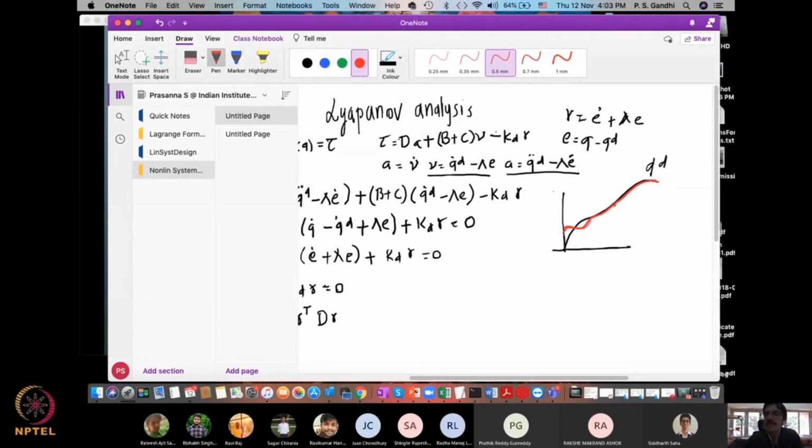Any trajectory that you are given which is a smooth, differentiable function of time, your controller is going to follow, with very small transients that will die down, and then it will completely follow the trajectory very nicely. Again I'm reiterating that we see this controller has these terms which are feed forward terms, these dA and b plus c times nu.